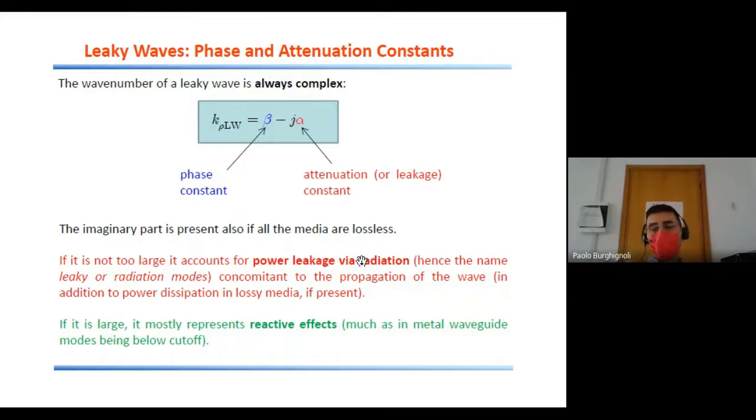That occurs also in closed waveguides below the cutoff frequency: modes do not propagate, but rather store reactive energy without transporting any real power. Something similar, even though not completely equal, occurs for leaky modes when the attenuation constant becomes too large. Generally, there will be a mix of the leakage effect and the reactive effect, and the transition between the two is not sharp, but blurred.